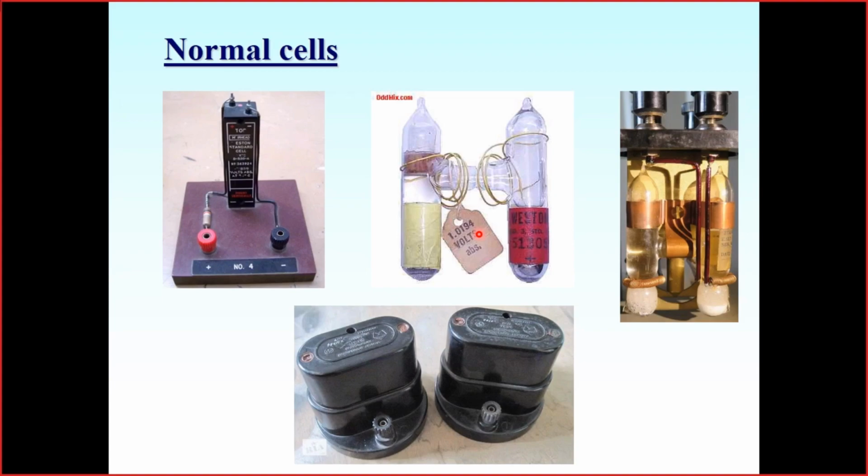So they couldn't keep a high current. If we try to load them, first of all, this voltage will drop, and second, the element actually depletes very fast. So we need to measure them with as low current as possible.